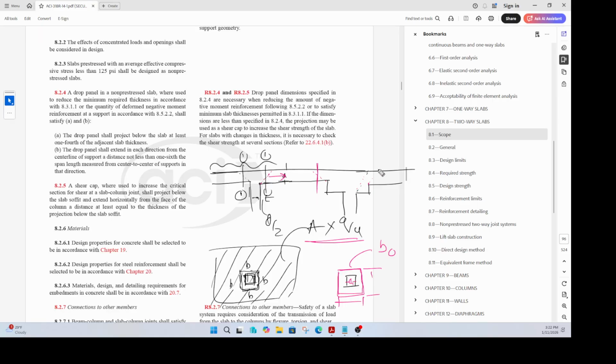So now your critical location 2-2 is that, right? Yes, there is a shear plane here, but then the depth is so much that you increase your area drastically. Whereas by pushing it here into this slab, let's say the thickness of the slab is d2, then the distance of that critical plane, which is this one, from this edge, right? That distance is d2 by 2. d2 is the thickness of the adjacent slab.